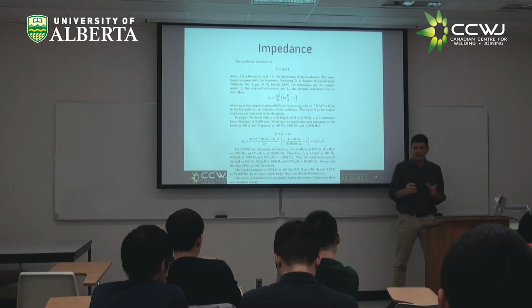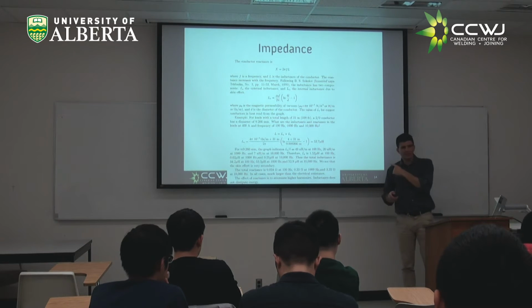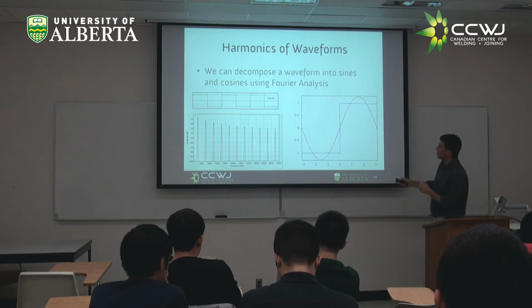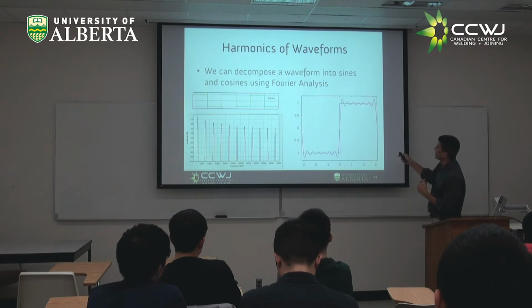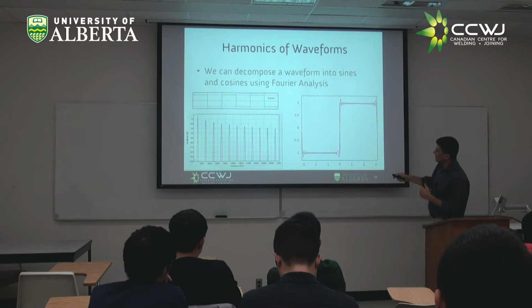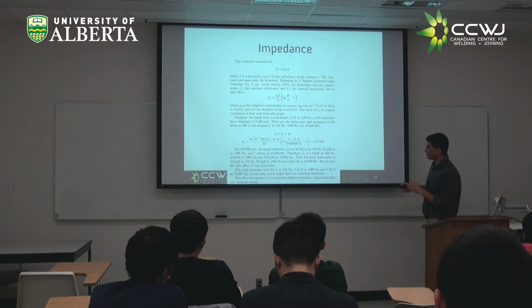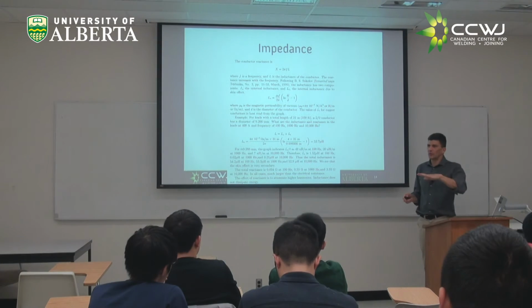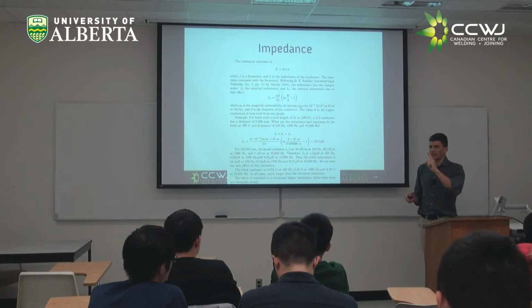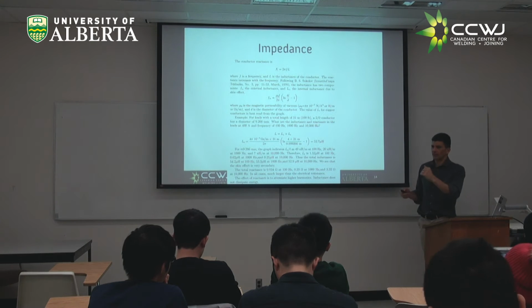So what is happening in the leads is the high frequency ones get killed first, right? So we start to round off our waveforms. In this example I have an animation in which, imagine you have a square waveform. The square waveform requires all these that are called harmonics. I'm going to do it again. It's going to start with the lowest of harmonics, one sine, and then it's going to be 2 sines and 3 sines and everything.